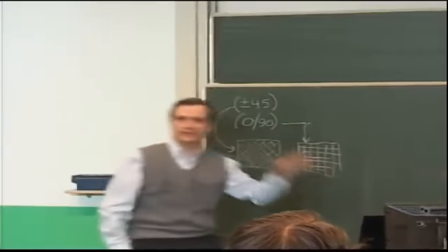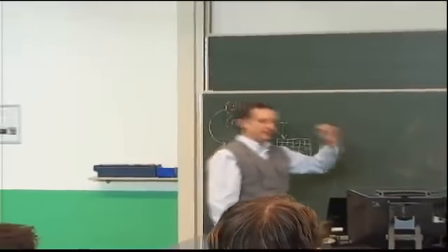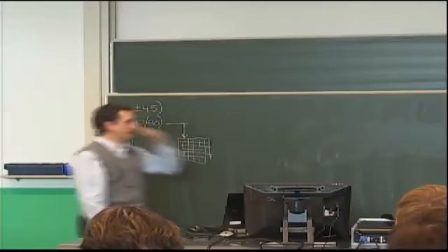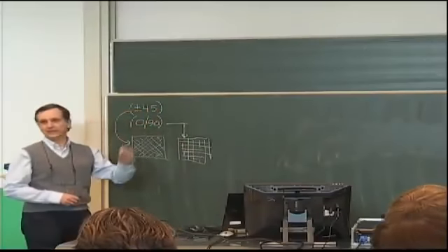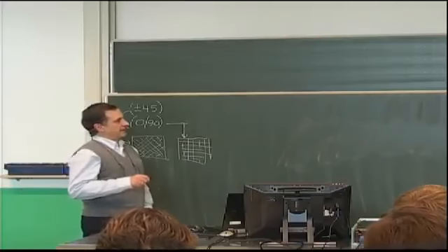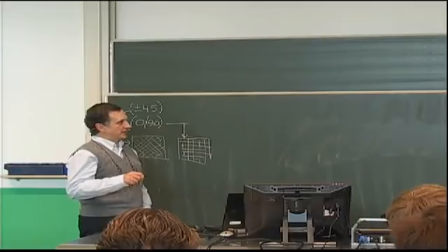The reason for doing that in this case is because D16 and D26 are 0, so I know that my assumption that went into the problem solution is definitely valid in this case. I'm plotting my axial stress, sigma x. Remember, x is running in this direction, and I'm starting from the top. X equals 0 is here.